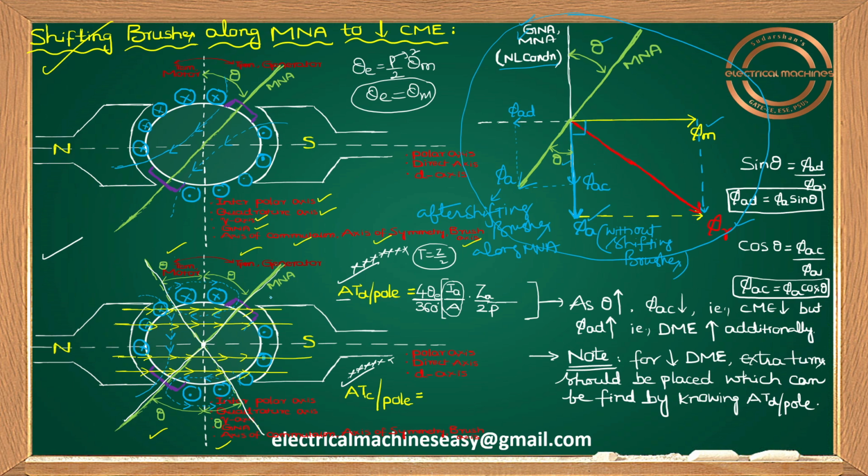It is out of the board, no? Out of the board means it will be anti-clockwise direction, like this. Okay, so observe clearly once again in this region also. What is the angle between armature flux and main flux here? I am asking the angle between the blue color flux lines and the yellow color flux, which is almost 90 degrees, right? 90 degrees. That means once again you are having a cross magnetizing effect.